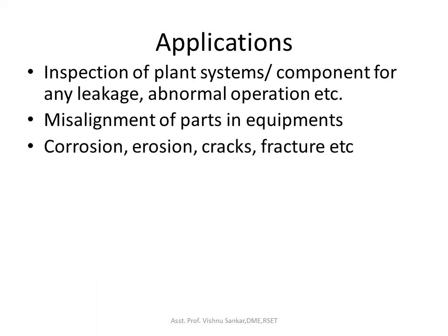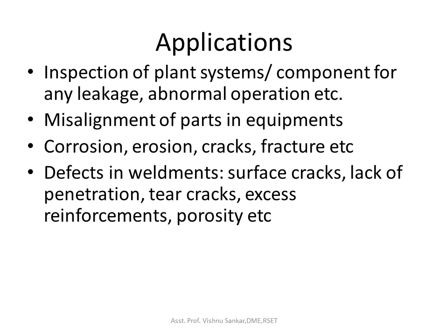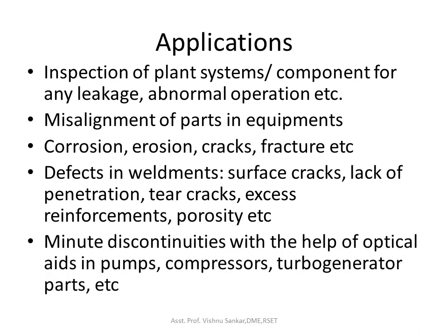Corrosion, erosion, crack, fracture, etc. can easily be identified with the help of visual inspection. Defects in weldments such as surface cracks, lack of penetration, tear cracks, excess reinforcement, porosity, etc. are easily identified. Minute discontinuities with the help of optical aids in pumps, compressors, turbo generators, parts, etc. are easily identified.